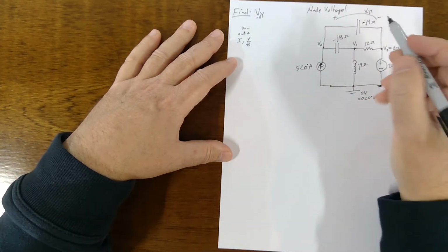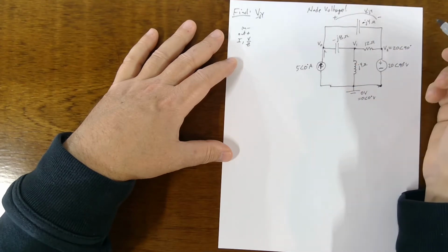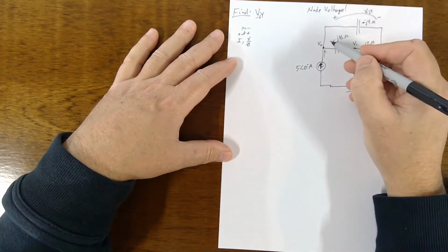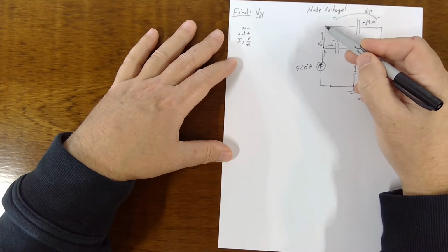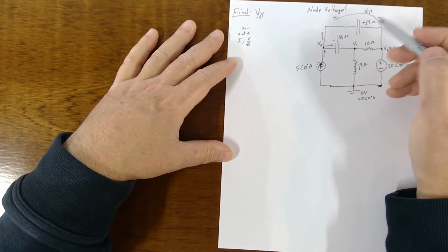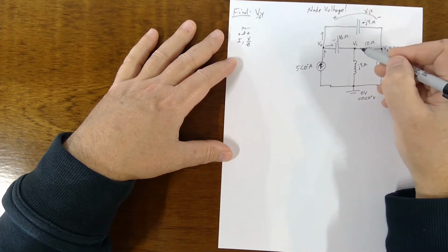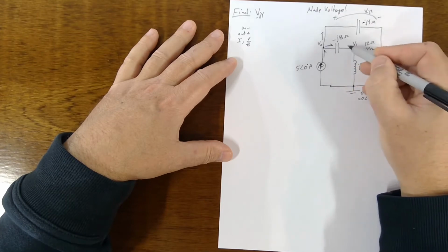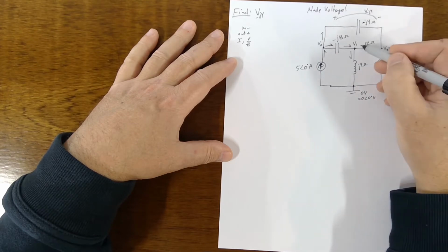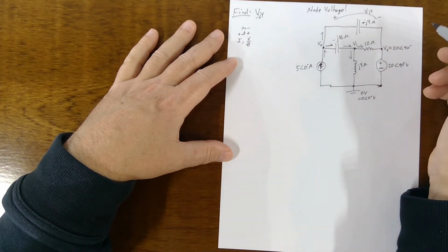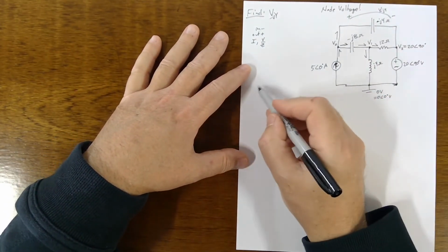So what's the next thing we do after we pick our nodes? We guess current direction. So we'll guess this way. We'll guess out, guess up. Up is nice because it'll go plus to minus and give us the polarity we want. If this is out, then just to be consistent, this is in, same arrow direction, and then guess that this is out, guess that this is that way. All right, so you guess these guys, then you start writing equations.